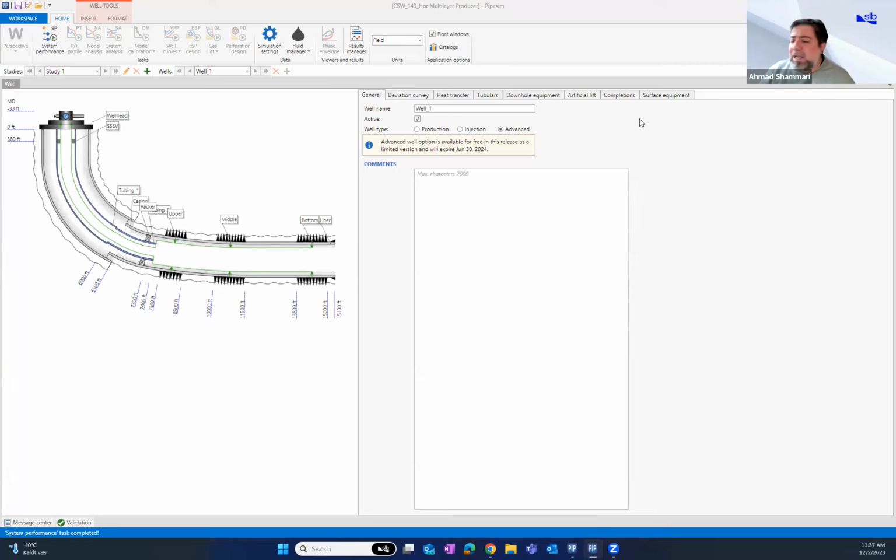Also, there is one calculation in PipeSim where you can put a valve and, as I showed earlier, just inject as much as you see, to see how much impact you have, because it could be that adding gas rate will never reach the rate that an ESP can give you.